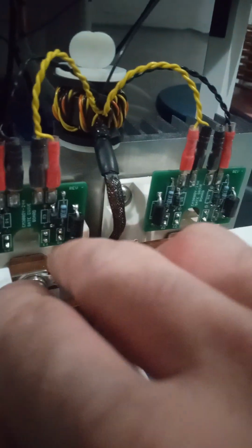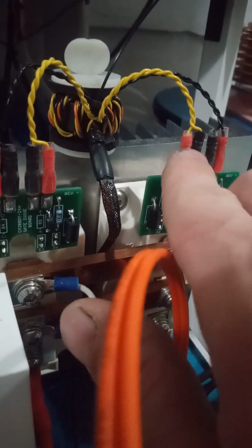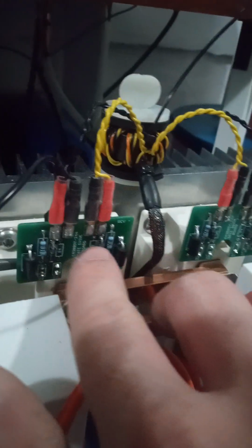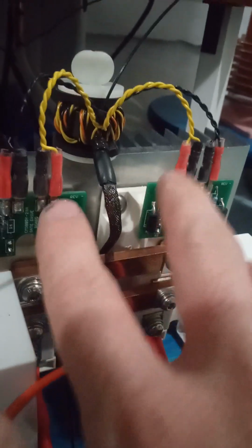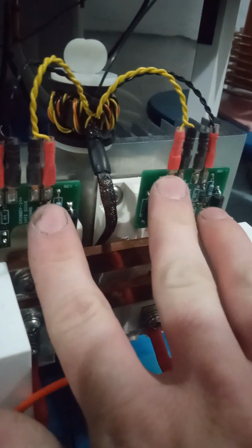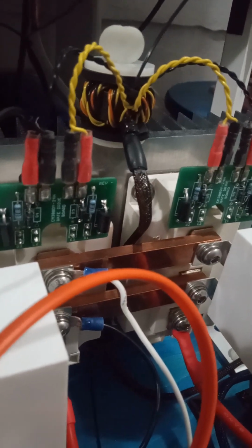And what I did accidentally was I wound this open end to this yellow open end. So they all were wound open, and I blew each half bridge in this IGBT, meaning one side of the bridge in each transistor. So with that being said, always make sure to measure your continuity.